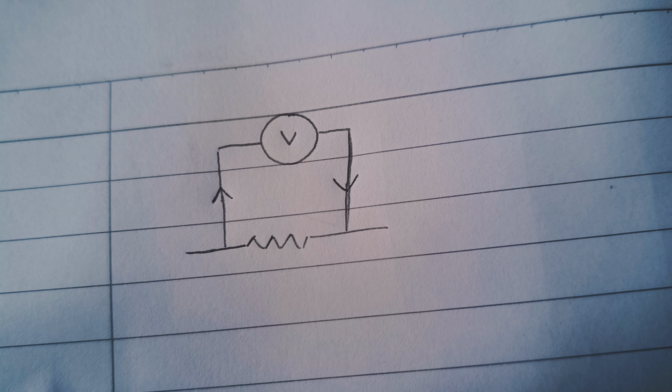In a nutshell, we can conclude that the multimeter value has a little bit of difference compared to the value of Multisim. This is because the multimeter value is affected by a few errors. Moreover, to measure voltage, we have to connect the probe in parallel, while for current, we must connect the probe in series.